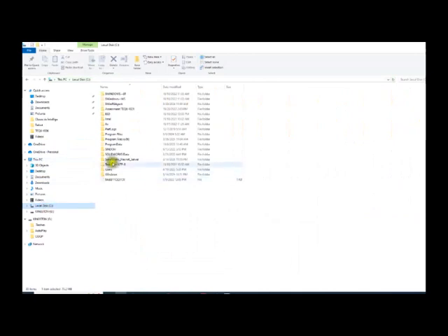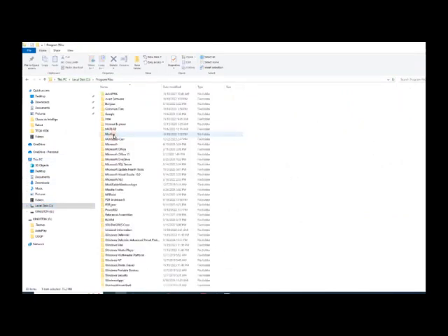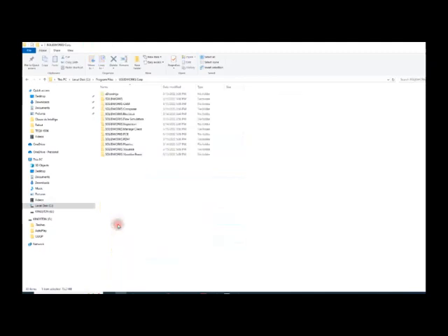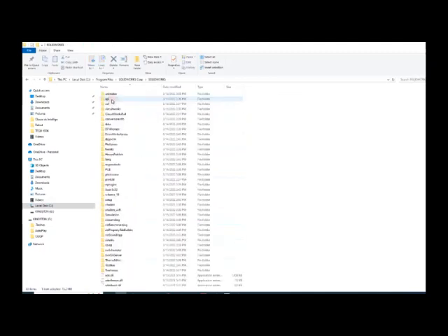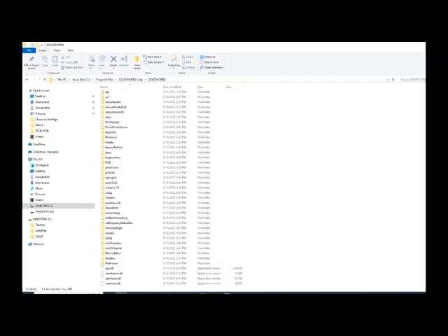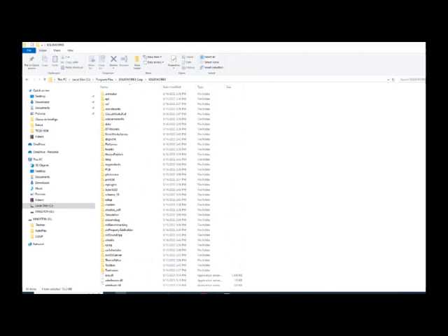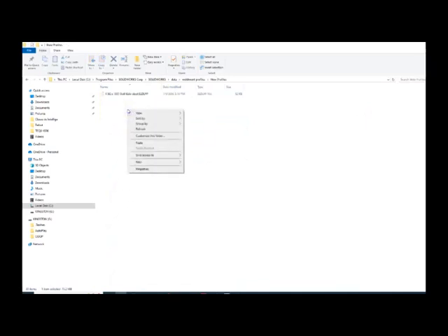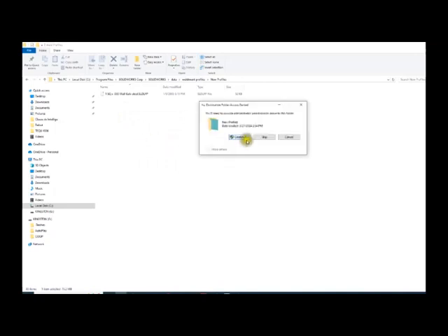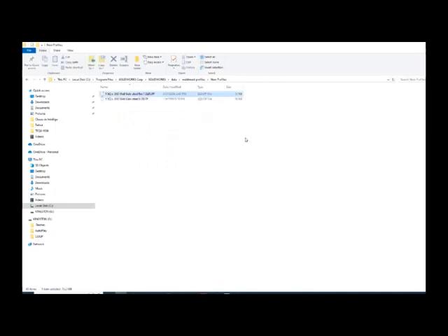All right, and then we're gonna go to Program Files. You see that, you get used to where your Weldment profile is located, because it's gonna get crazy. So where am I? SolidWorks. I need to go to data, and then from data, Weldment profile, new profile, and let's see. We're gonna paste it there. Paste. Continue, and bingo. We have it there.